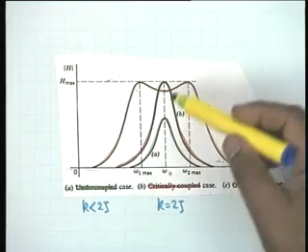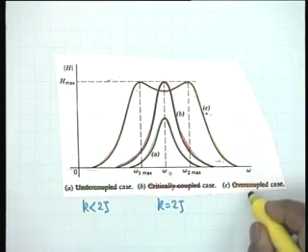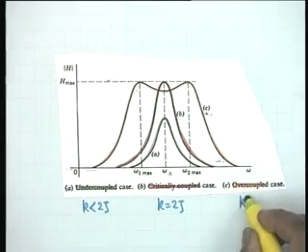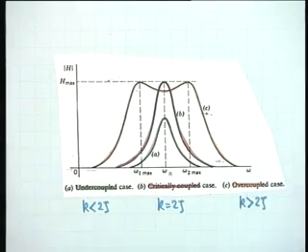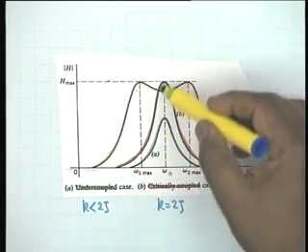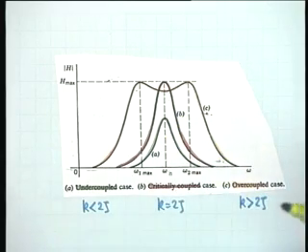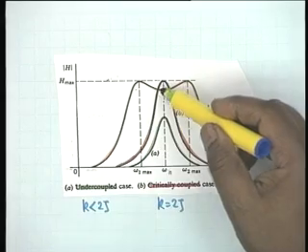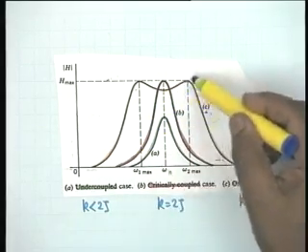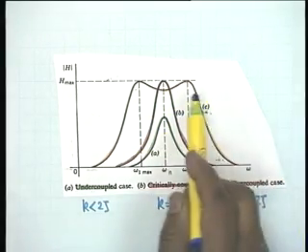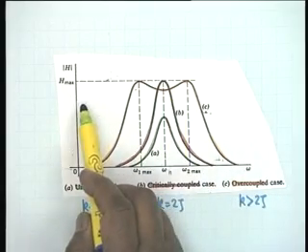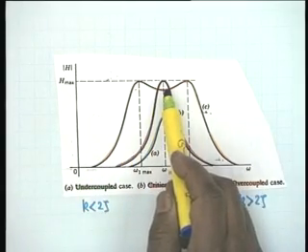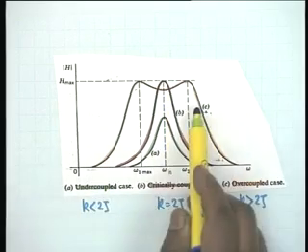Okay. When it is overcoupled, when the coils are brought close to each other, that is K is greater than 2 zeta, this single resonance curve now flattens in the middle to make way for 2 maxima. And obviously, as you can see here, there shall be only 2 half power points. This is not 70.7%.